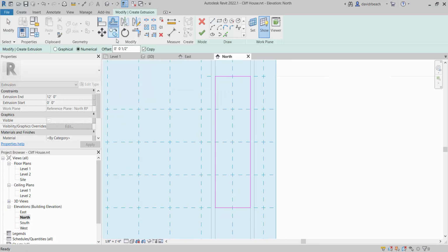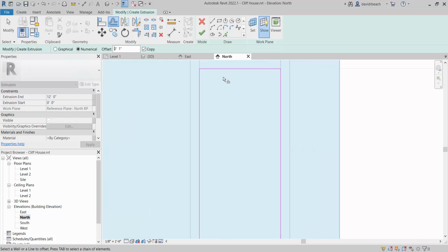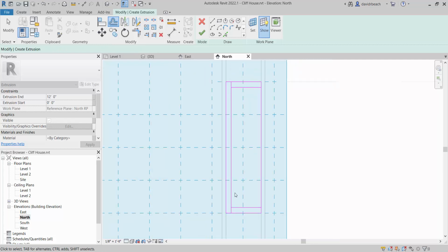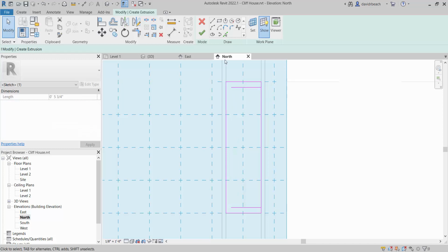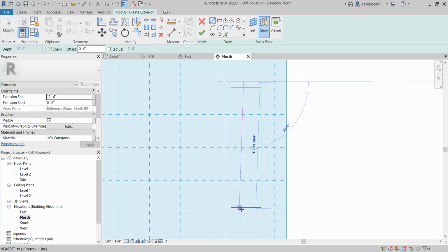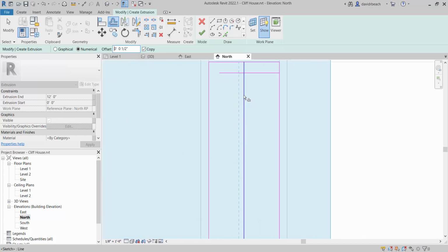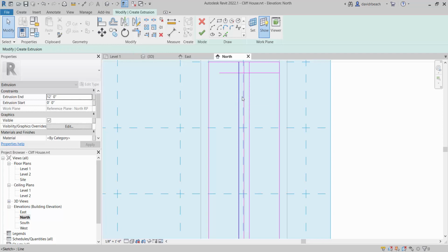So let's go down 2 feet. Across. So again, I'm boxing that out. Right? I'm going to run my offsets. 1 inch. Oh, I really should do top and bottom, not just on the side. Center line to center line. Offset 1/2 inch, to make the flange.